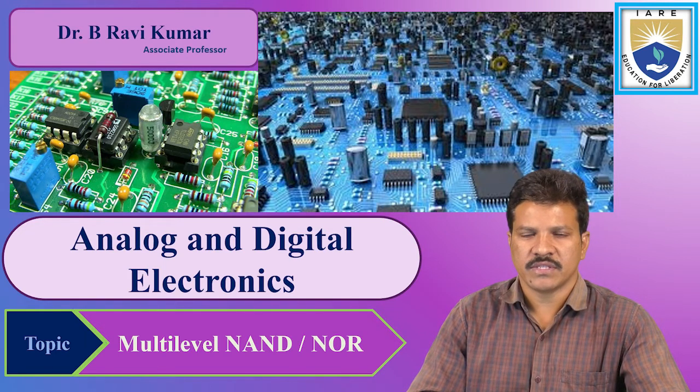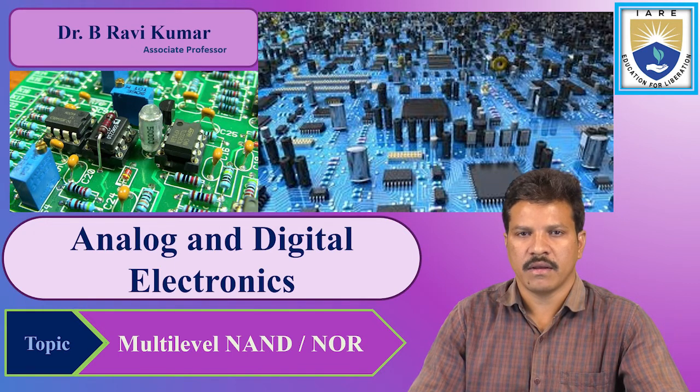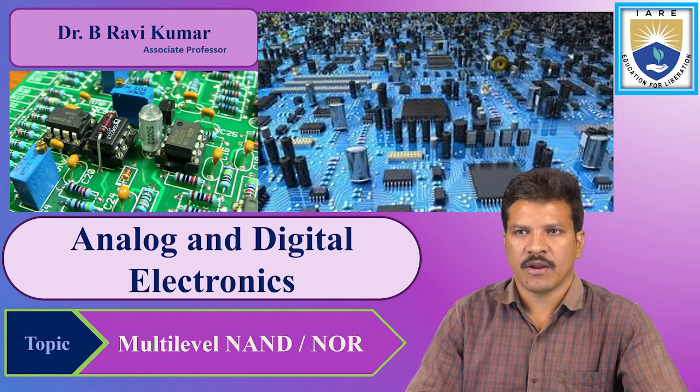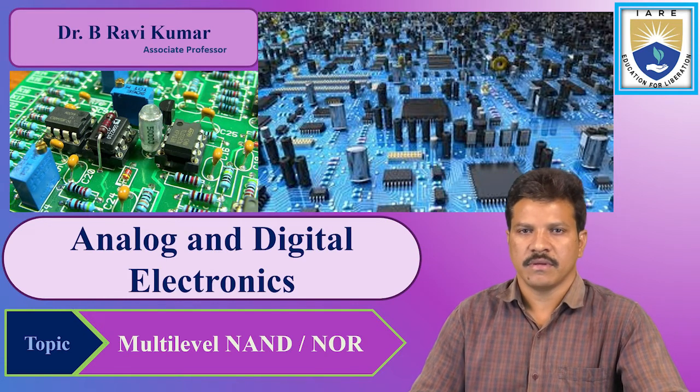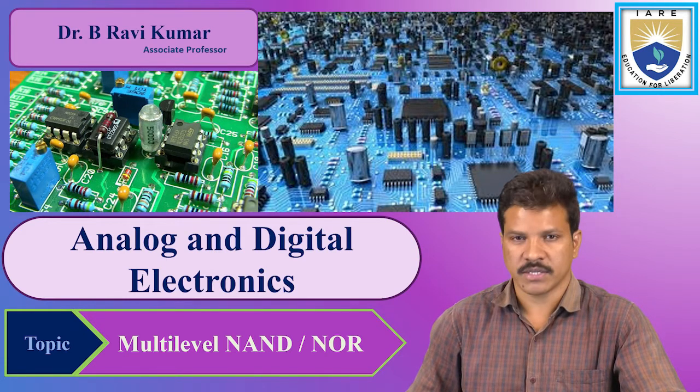When we see those simple conversions from NAND and NOR into AND or inverter, they are like two-level gates. Now we will see multi-level NAND and NOR implementations. Any combinational circuit can be implemented by NAND and NOR circuits.